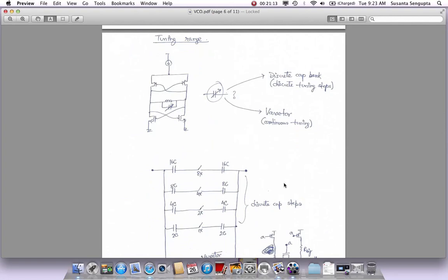Now this is only with respect to the receiver I've talked about. The same VCO can also be used in the transmitter, and there you have similar requirements, which is: if I go outside of my transmit band, how much noise should I be pumping into the air or into somebody else's frequency band? If you know that number, you can derive back what your phase noise requirement for the TX should be. So that's also another way to derive the phase noise numbers.